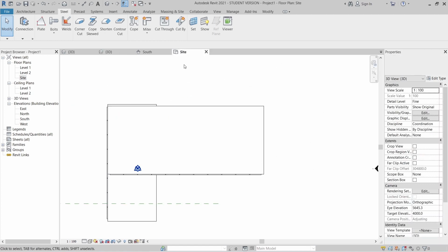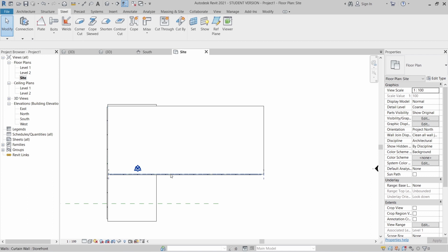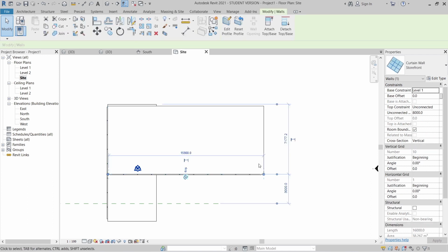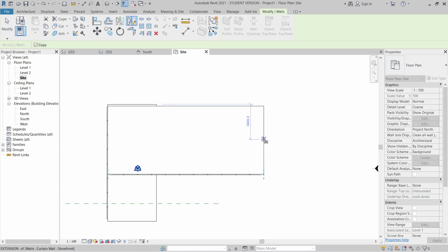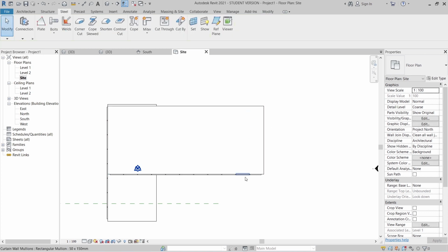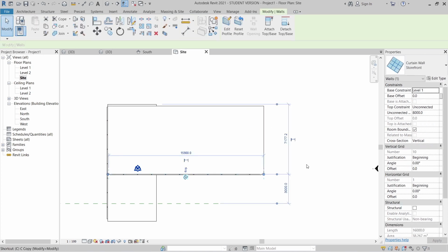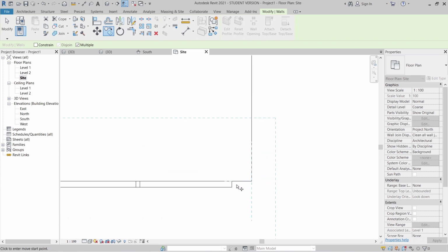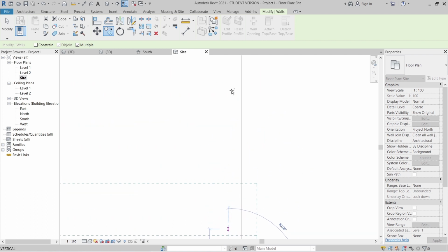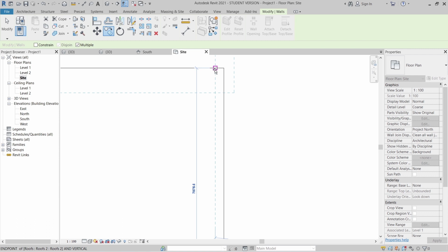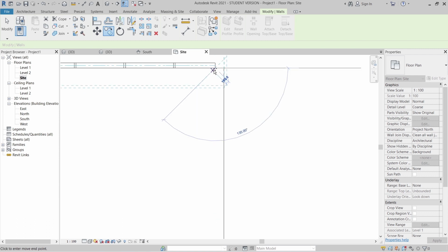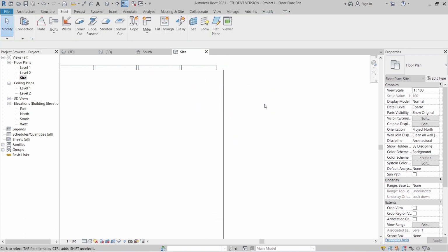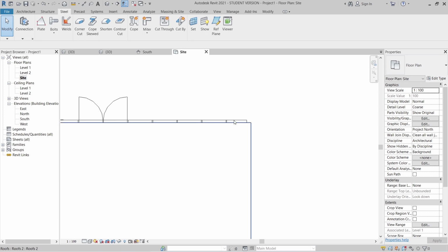I need to copy also actually. Then I can select here, then try to use mirror, the shortcut key, cannot. I think we could not because we cannot find our center point here. Then I can select my full curtain panel again, Ctrl+C for copy, start from here until here, then hit escape a couple of times, select my panel here.